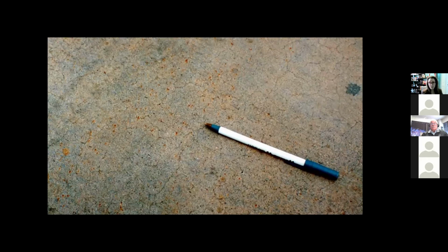Is this a problem? Well, it sounds interesting. It actually can be. It depends on how much sand is in your mixture and how reactive that sand is. And some sand is very reactive. So it could structurally change the concrete. It could cause map cracking to open up. It could cause volume changes in your concrete. This can happen in interior concrete and exterior concrete.